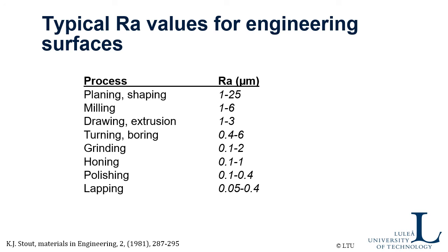So you see here that we are down to 0.05 micrometers. So it's 50 nanometers then. So it's a very smooth surface. Depends also, again, on how long the L is in the measurement length.